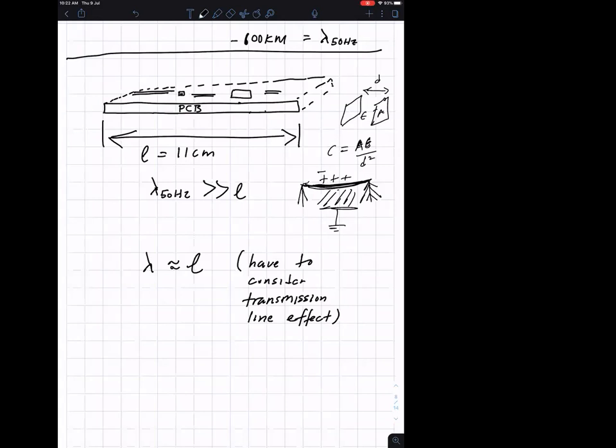Another way the capacitance can be increased is when you increase the area. Another way capacitance can increase is if you increase the dielectric. So the dielectric was air, but when it was drizzling, the dielectric is different. And somebody got electrocuted and died due to capacitive coupling.